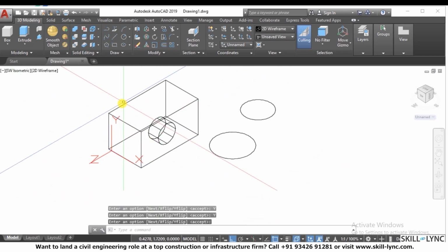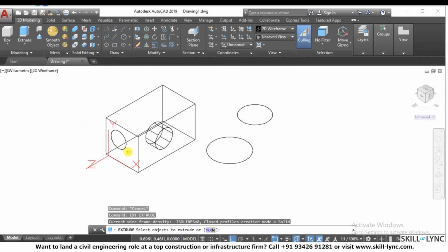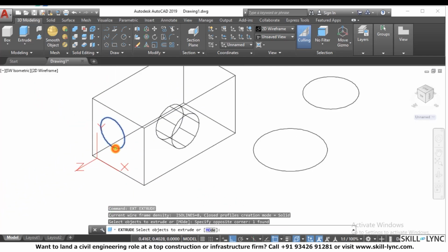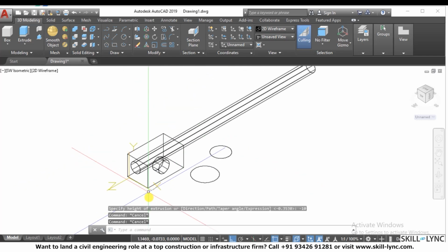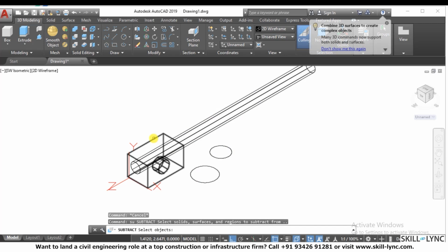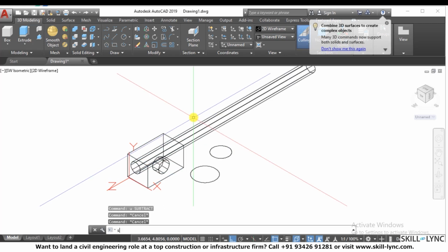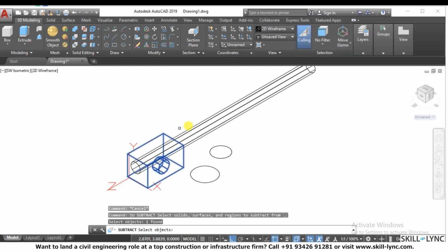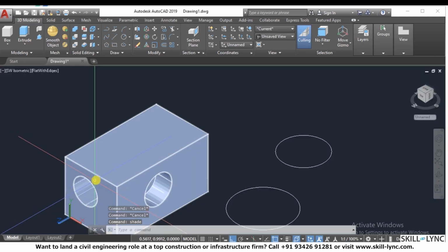Press enter to accept. So now if you create something, if you create a circle again, it will be created in this face. Now, if you want to create a cut inside, you have to go negative Z. So I would go for minus 10. So it is cutting through. Minus 10 is huge. So you can go for a subtract. It will cut the hole through. So how do I go subtract? Subtract, select object this box, and this cylinder is the other one. So you can see that if you shade with the shade tool, it is cutting through.